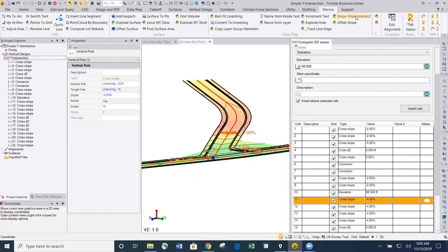They can be offset vertically or perpendicularly now, and that will calculate where the subgrade meets the offset of the side slope. So you can find, like, a topsoil strip on the embankment and a 2-foot offset for the center line to edge of pave, and it will calculate the intersection strings and all the offset strings, so you can build a subgrade surface really fast.